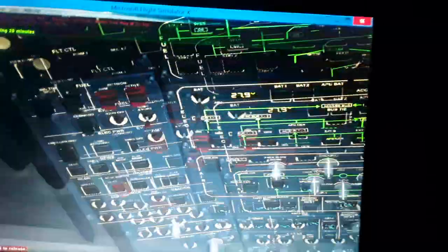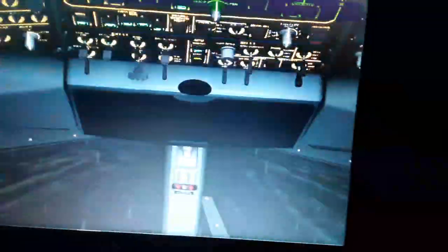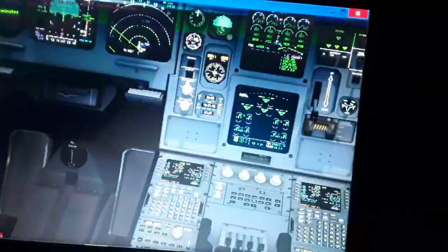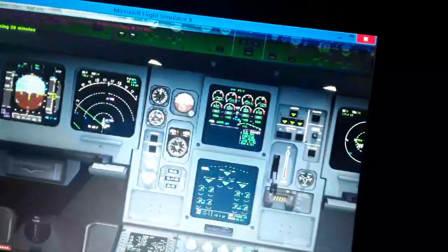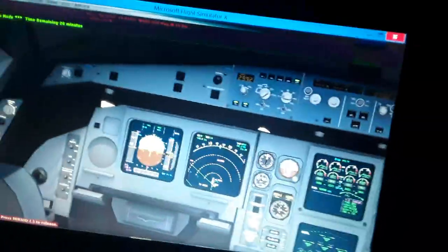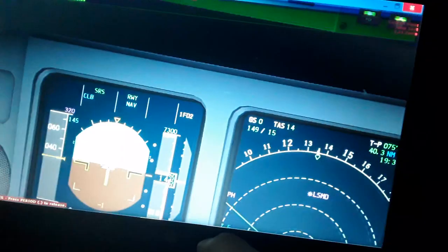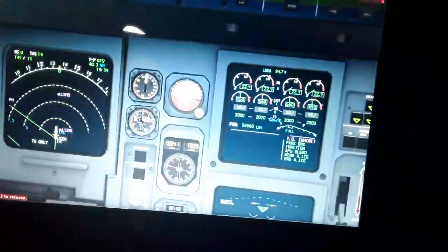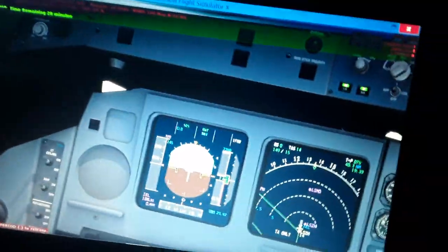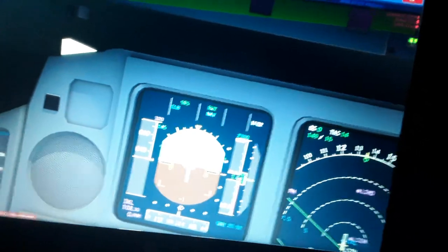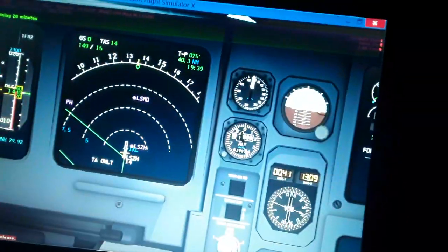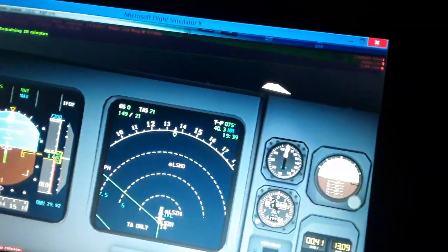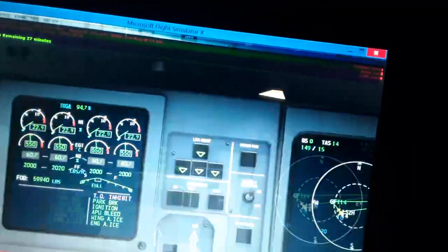and it uses the data inertial reference system over here for GPS and acceleration, gyroscopic acceleration, and other data like magnetic or true heading, and also air data from the pitot static, which is used for barometric altitude and airspeed setting, and also pitot static, pitot dynamic, which uses moving air.